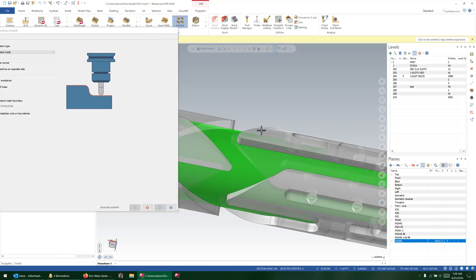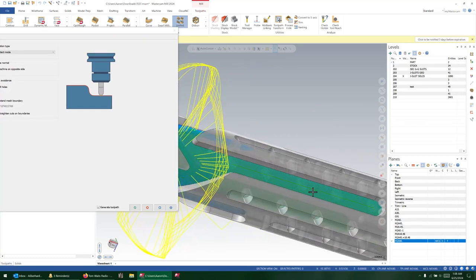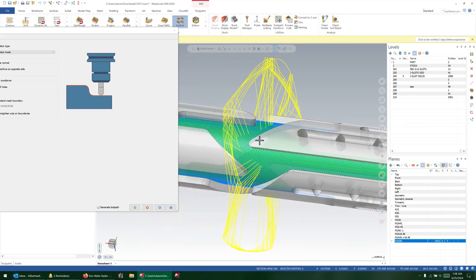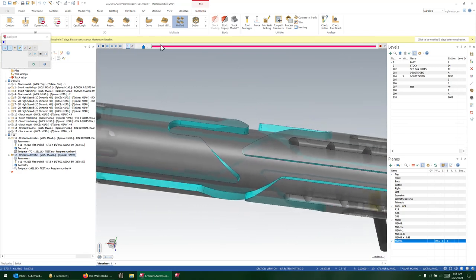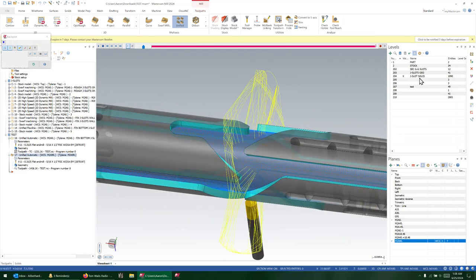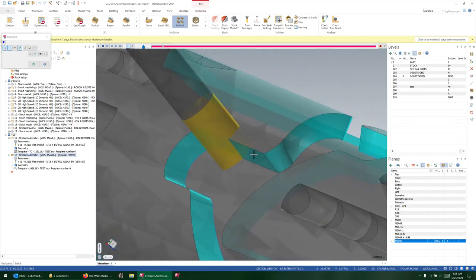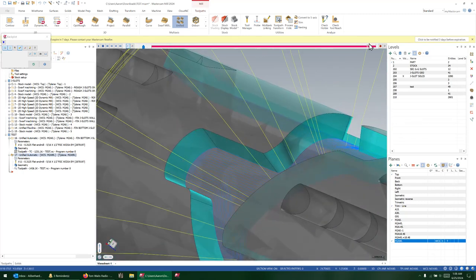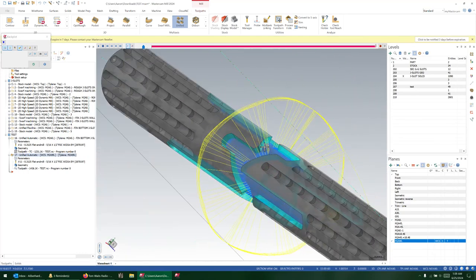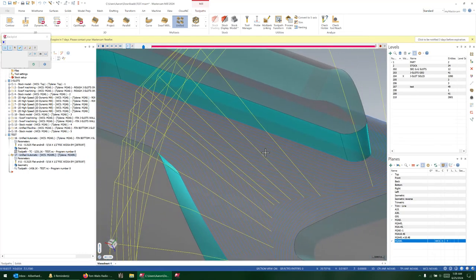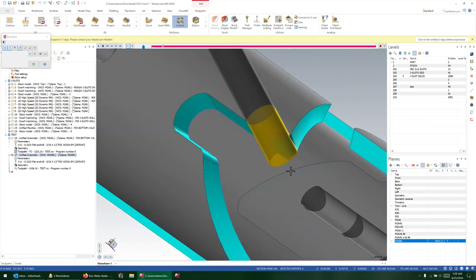I'm going to slide this out of the way while it generates that toolpath. Okay, hey, look at that. Beautiful, beautiful toolpath right off the bat. But of course, this doesn't necessarily solve this problem. So it looks pretty on the screen, but of course the reality of it is that as we look at it, it's cutting right to the center here. Now, also the linking could, of course, be improved a little bit, but as you know, we deal with linking last. So let's deal with this first problem of the tool plunging through the wall.